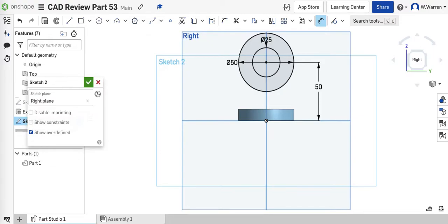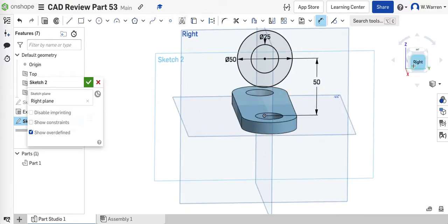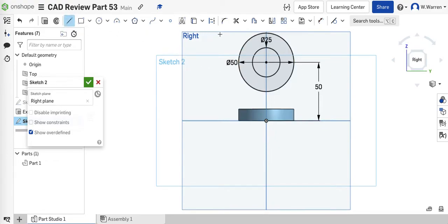Now what I think we should do is, let's see here, we've got to draw some lines straight down. So let's draw a line straight down. I think again I'm going to use the same technique where I just make sure I draw a vertical line. Make sure that's vertical. And same thing over here. Just make sure it's vertical. We'll trim it out and place it. The tangent tool is still lit up, so I just want this tangent to that. I want this tangent to that. And to close out the geometry and make this not an empty space, we just have to connect here to here, right? So let's do that.